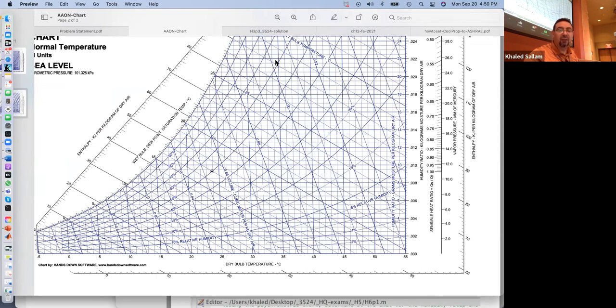So here's 30. If I cool to 30, I'll become like this, same W. 25, I will come here, slightly smaller W. But if that cooling coil can take me to 20, compared to where I was at 35, when you read the W omega over here, it's 0.022. And if I go to 20, I will go to 0.015. So 0.022, you see where I'm reading?